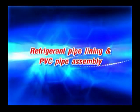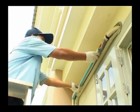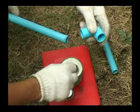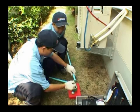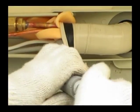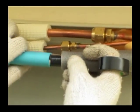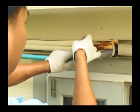The refrigerant pipe lining and the PVC pipe assembly. Determine the right length of the PVC pipe. Assemble sections of the PVC pipe with pipe glue until the pipe line reaches the drainage area. The refrigerant pipe and the PVC pipe should be tied together. Connect the drain hose of the indoor unit with the PVC pipe of the outdoor section.